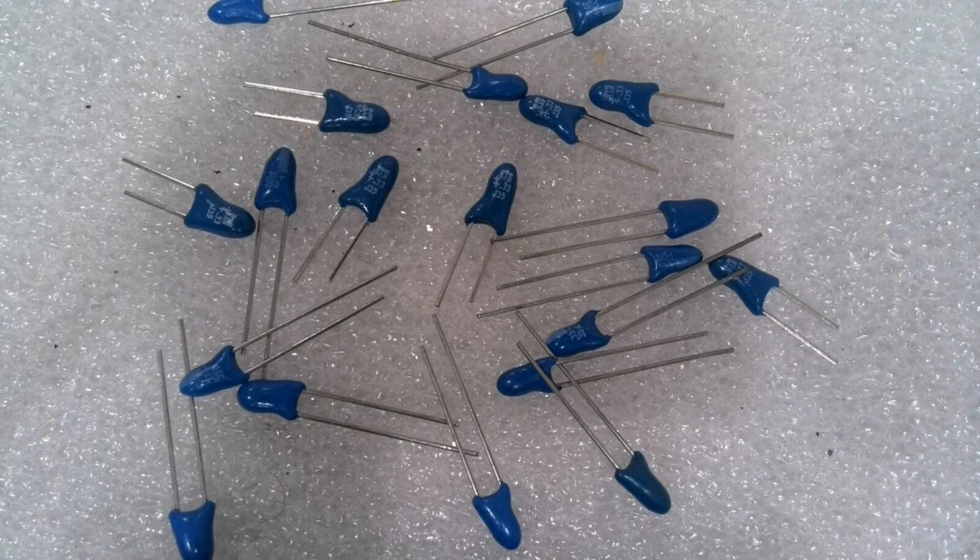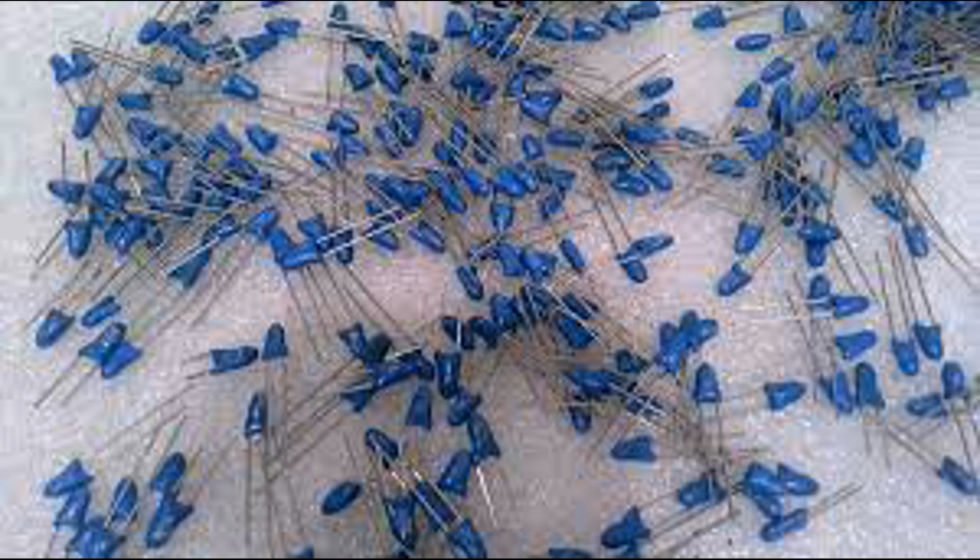Construction diagram, simplified. Anode, tantalum pellet, porous, connected to a lead. Dielectric, tantalum pentoxide layer formed on the surface of the tantalum anode. Cathode, manganese dioxide or polymer layer covering the dielectric. Carbon and silver layers improve electrical conductivity and connect the cathode to the external circuit. Encapsulation, protective casing around the capacitor. This careful construction process is what allows tantalum capacitors to provide high capacitance in a small package while maintaining reliability and stability in various applications.